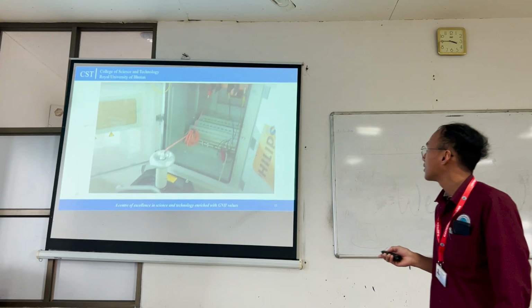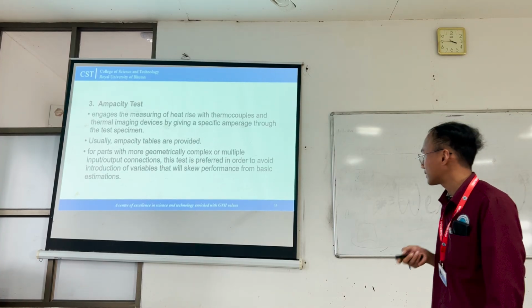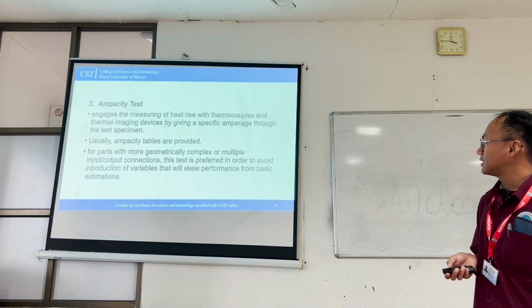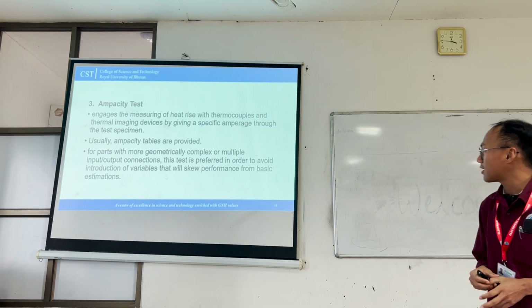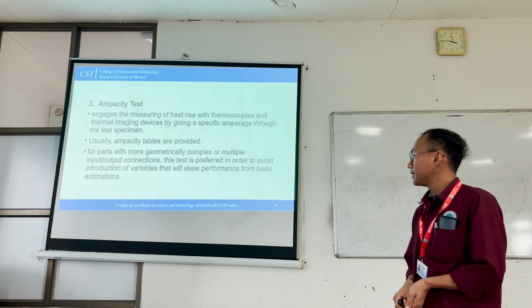Now, lastly, for busbar testing, it is the ampacity test, where it directly measures the heat rise using thermocouples and thermal imaging devices by giving a specific amperage through the test specimen.